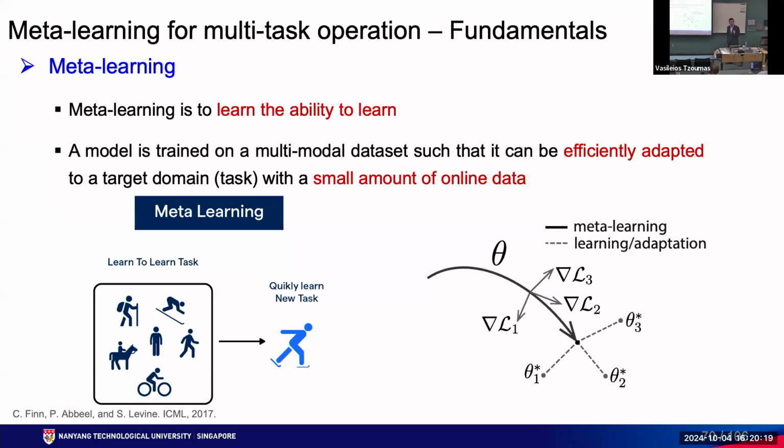This is the idea of meta-learning. If we translate it into process control terminology, I can handle the first operating condition well, and the second operating condition well. When I face a new unforeseen circumstance, I just use a few new data points to adapt to this new environment very quickly, instead of performing neural network retraining.